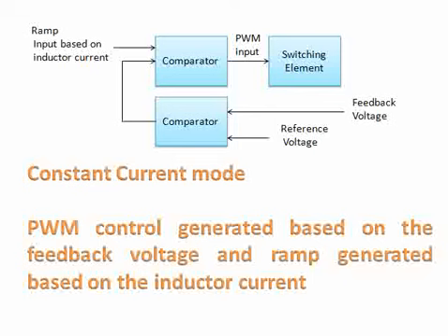While there are advantages with this mechanism, where it brings more control, there are also disadvantages. If the current is varying continuously and the current sensing is not proper, there might be a chance that the output voltage is not constant. So there are disadvantages and also advantages. Fine control is one advantage, and the stability we talked about is another point to consider here. That's the major difference between constant voltage mode and constant current mode.